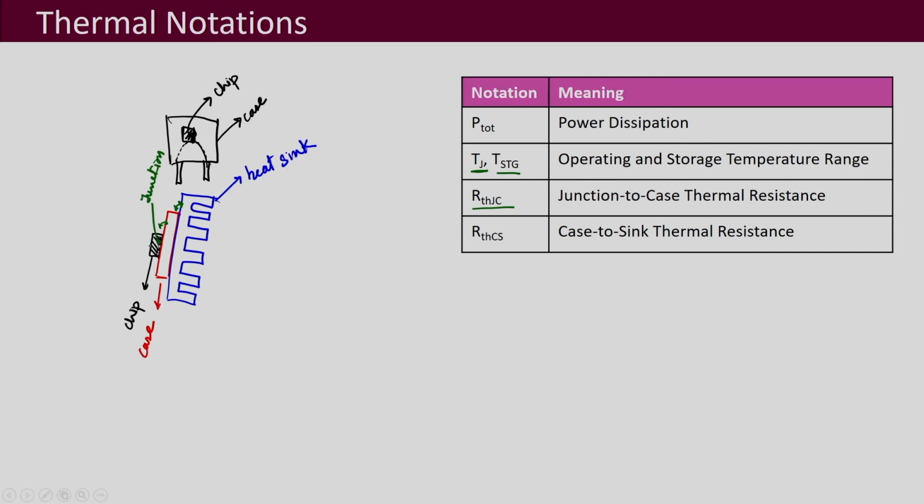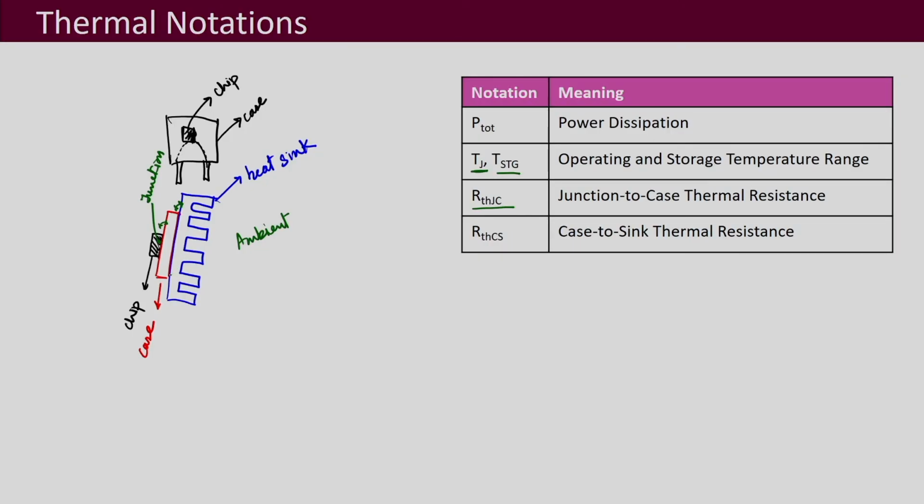So, what is the thermal resistance to the cooling? Junction to case there is one thermal resistance, then case to sink there is another thermal resistance, and sink to ambient. So, this is your ambient. It also has a temperature, which you may call the room temperature, but ambient temperature may not always be the room temperature, it depends on what environment the converter is being operated in. So, the sink to ambient thermal resistance is also there, but that you look into the heat sink's data sheet. In the device data sheet what you see is this case to sink thermal resistance will also be provided.